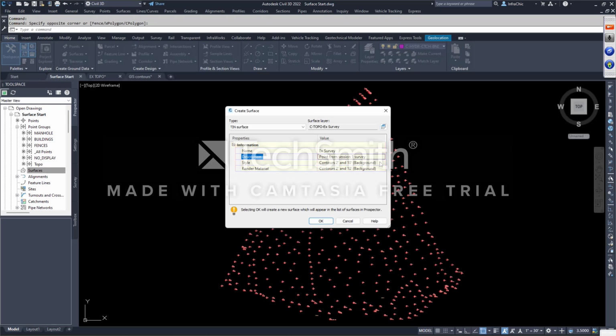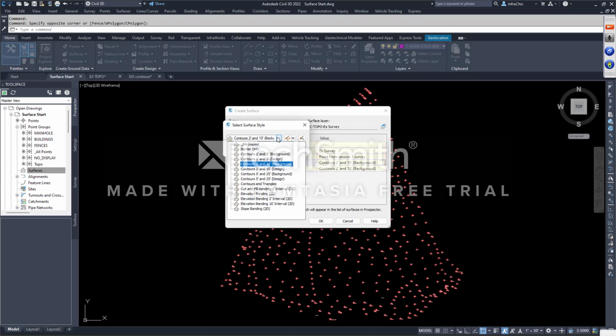Style, the initial style set that you want displayed after you put stuff into the surface once you start filling in the holes. This is just, you're creating the object name to put stuff into the object. So this is the initial creation point. What style? I select once, I get the multiple ellipsis more button. I select the more button again, and I get the select surface style dialog. Every time you see that more button, that means there's a dialog box that you can access to select something further.